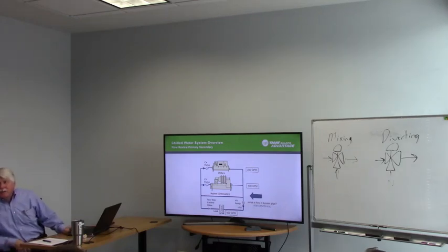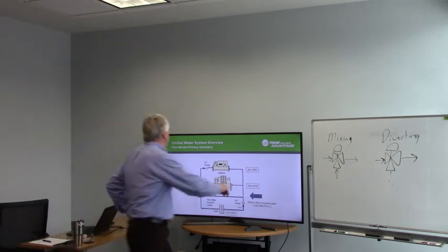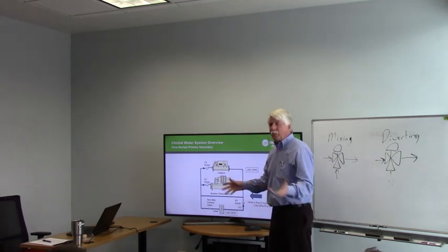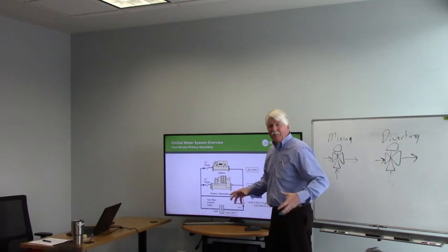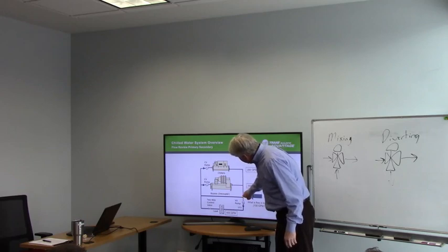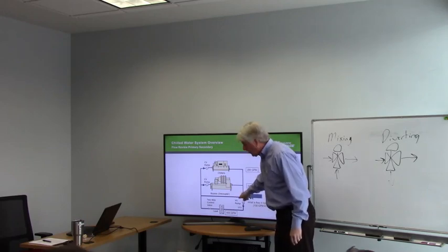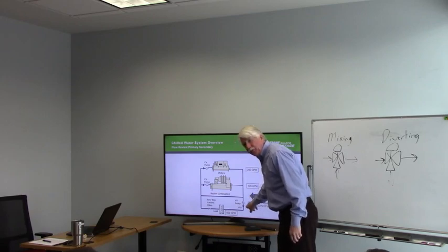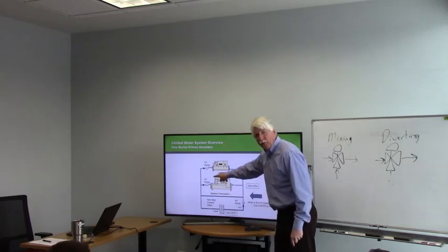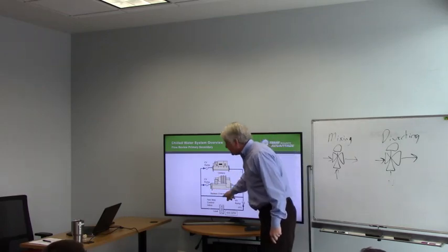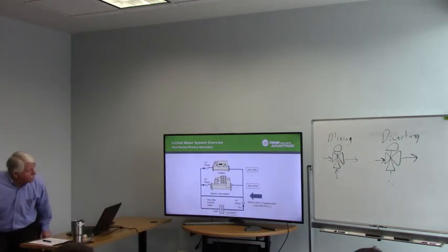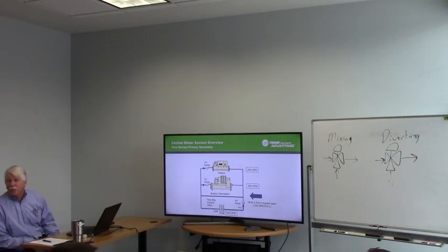Now, does everybody see that? At this point right here, I have 700 GPM that has to go somewhere. By the way, water is not compressible, okay? So I can't have different things happening in the same system. So I have 700 GPM entering this T here, okay? And I have 600 GPM going out this port of this T. So that means there has to be 100 GPM going across that way. This thing is called a decoupler, and it allows water to move back and forth depending on the system load.